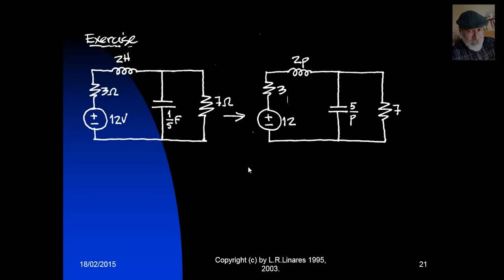And then what? And then we solve the circuit using modified nodal analysis. You say, what are you going to find? Well, they should tell us what we want. We want to find a differential equation. For what? Let's say we want the differential equation for the voltage in that node 1. Reference node, node 1, branch currents, chosen like that.